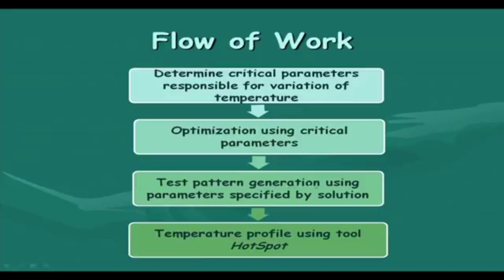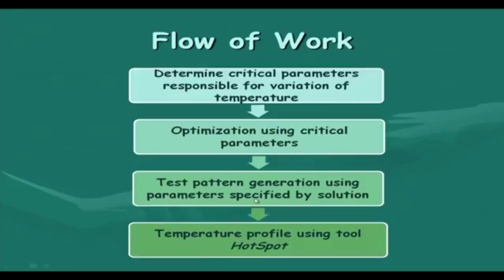Then this test pattern generation will be done using the parameters specified by the solution. So, this solution will tell us what the typical critical settings for the LFSR are, and based on that we can do these things. Now, once we have done this test pattern generation, we can do a thermal simulation using, say, the tool HotSpot or a similar thermal simulation tool to get the temperature profile of the resulting situation.